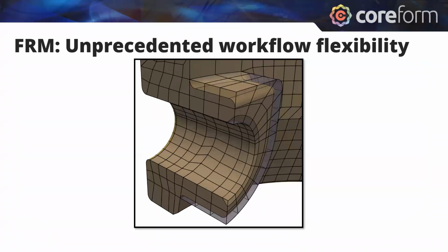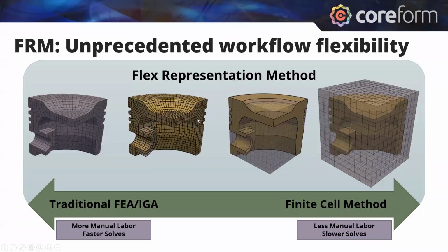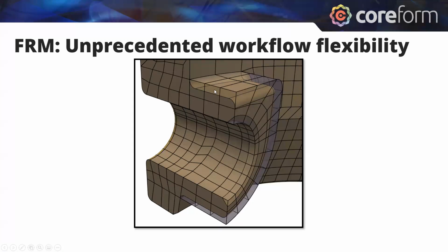And so in this case, it's second here from the left, everything is body fit. The one challenging part were these shoulder fillets. And so what we've just done is we've just immersed those regions. Now this is essentially, it's still really easy to mesh. It takes 5 minutes to mesh this part once you have this immersing region here. And so this is likely to get you rapid convergence to properties that you care about, maybe in this region.